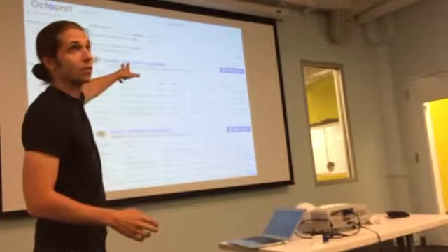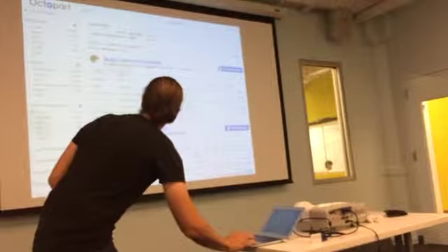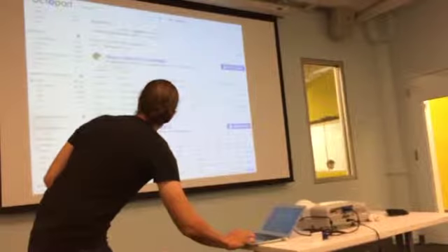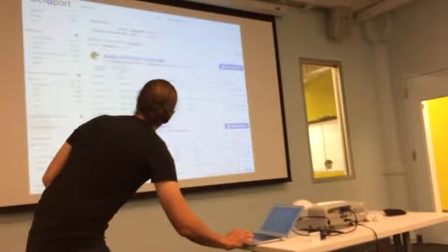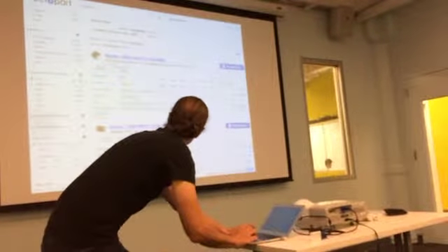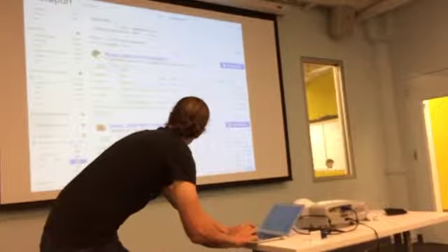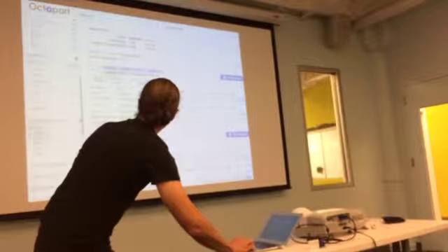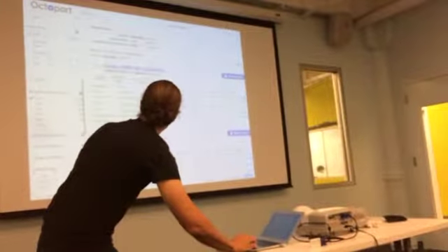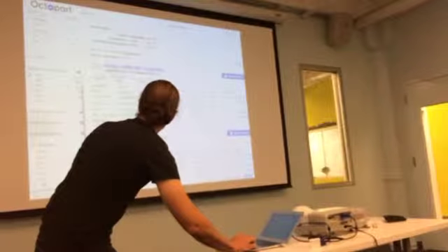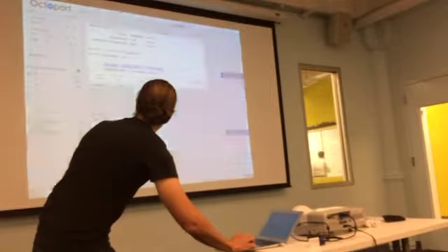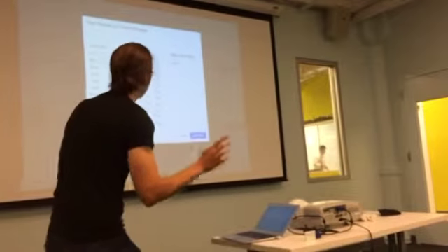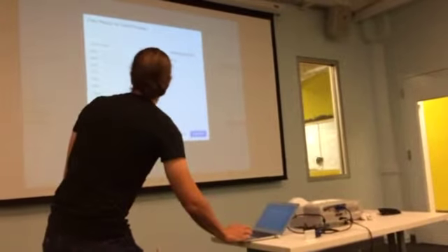Now we're down to 86,000 capacitors. Okay? And now let's go to capacitance. I said I wanted 1 microfarad. So set exact value, 1 microfarad. Now we're down to 2,000 capacitors. And case package, I said I wanted an 0603. But I think it's too big. Oh wait, oh yeah, here they are.